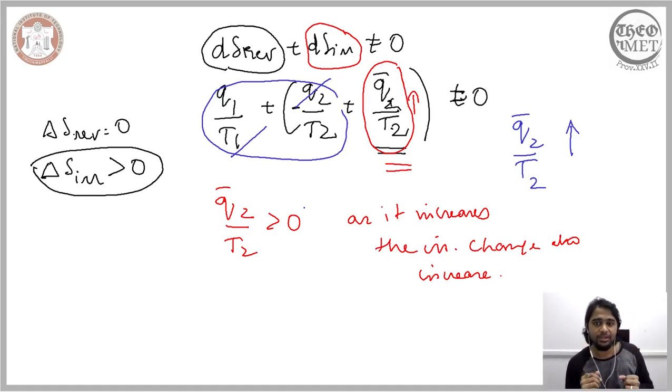So from the second law of thermodynamics, by looking at the dynamic system, we are now able to state what type of dynamic system it is. Is it a reversible system or an irreversible system? For a reversible system, we essentially have no overall change in the entropy. However, in case of an irreversible change experienced by the system, there is a continual increase in the change in entropy. So the second law of thermodynamics has now given us two criteria to distinguish the dynamic nature of this system.